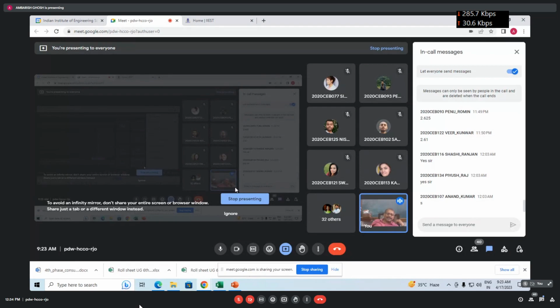Now, in case the moment is high, then up to the depth of fixity, you will be providing more reinforcement. Then you give your development length, and below that you can give less reinforcement. But in a tension pile, you give the reinforcement throughout. Don't curtail it. In case of tension pile, as you know, if you design a concrete member under tension, the reinforcement only will take the tension, and concrete takes very little, which we neglect in pile. So you can design the structural part also.